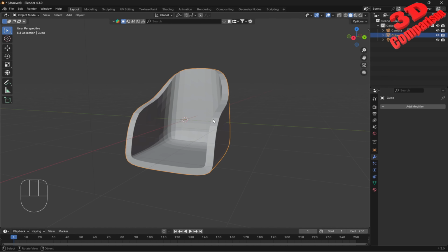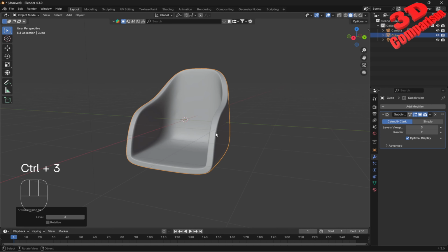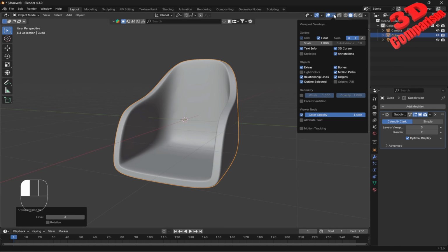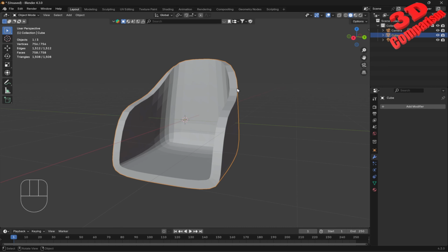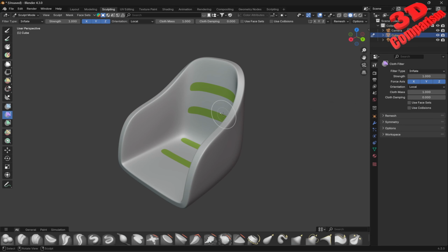so it would be wise to go back over here within the sculpting environment and apply another subdivision. So I can just press Ctrl 2 or Ctrl 3. Ctrl 3 will give us even more details, since this will be a level 4 viewport. If I'm going to enable over here the statistics, we're going to see the total number of faces over here. So almost 50k in this case. And we see without that, it only had 758. So with the subdivision level 3 applied,